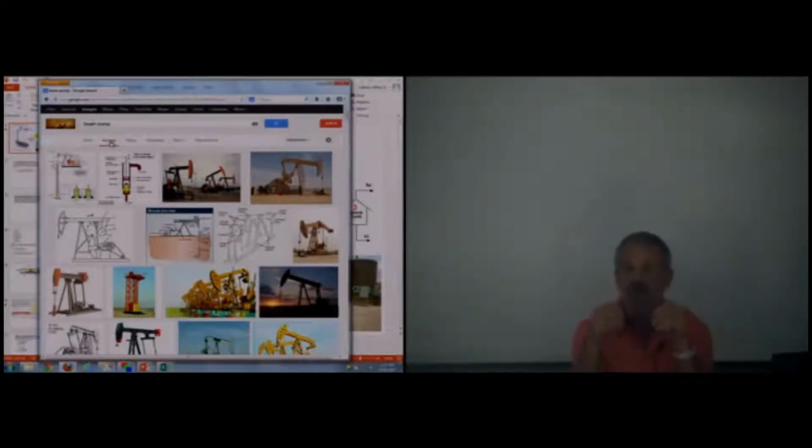Now, if we're producing primarily liquid, this is all important. The liquid gradient in the well is much higher. What is the liquid gradient of water in PSI per foot? 0.433 if it's fresh water, a little bit higher if it's salt water, 0.46. What if it's oil? 0.3 is a good number. And what about gas? 0.08. I usually use 0.1 because I'm not that accurate.